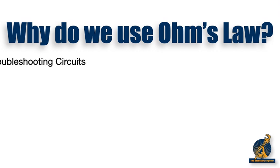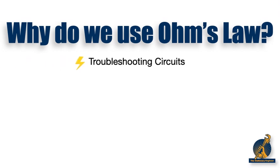So why do we use Ohm's Law? Well, we can use it to troubleshoot circuits. We can mathematically determine what should be happening in the circuit before we actually place a meter into the circuit or analyze the circuit. We can mathematically determine what should be happening and then go out and measure to see if what we measure matches what we have calculated.